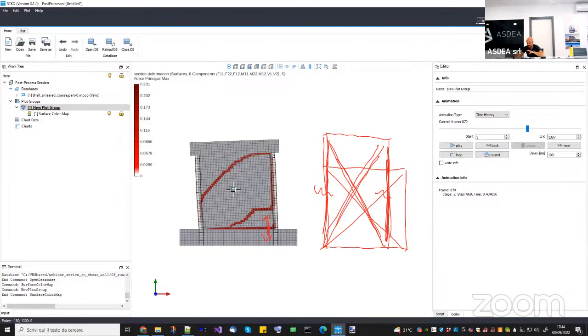So that's why I was saying, when you use a homogeneous model, you should expect that you damage a little bit before the reality, because actually I'm spreading the damage in all the directions. If I have a certain crack, it's like my material model is cracked in every direction.